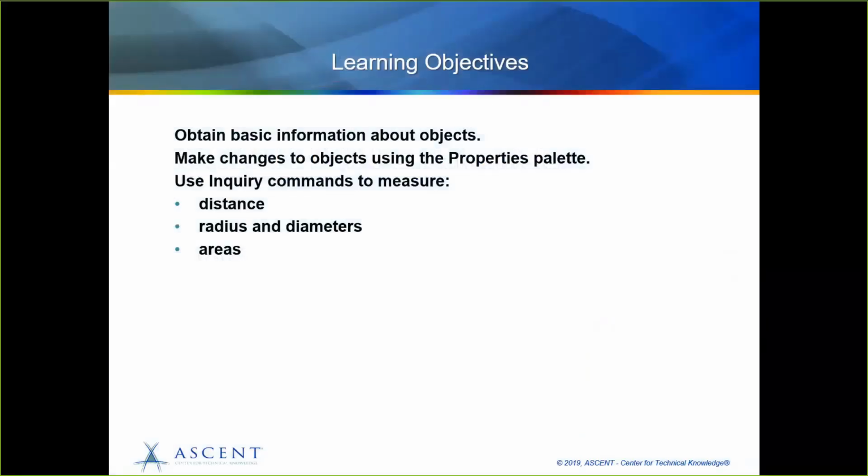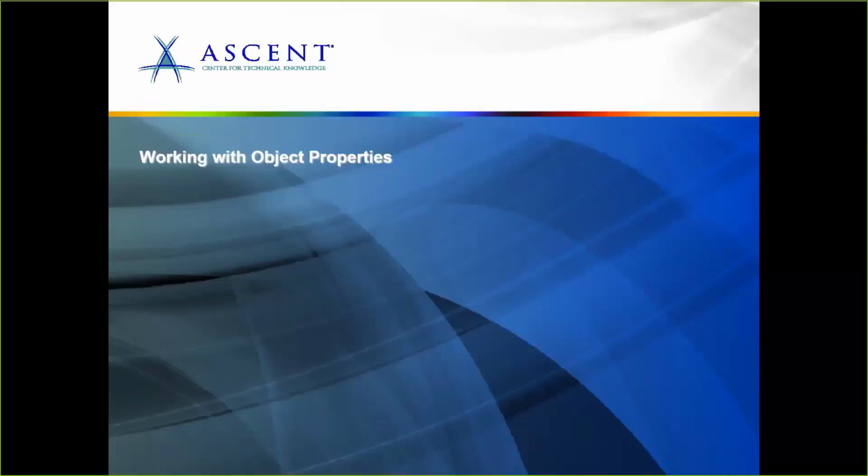Now the learning objectives are to obtain basic information about objects, make changes to objects using the Properties palette, and use inquiry commands to measure. We'll be measuring distances, radius and diameters, and areas. Now, first of all, we'll start with working with object properties.